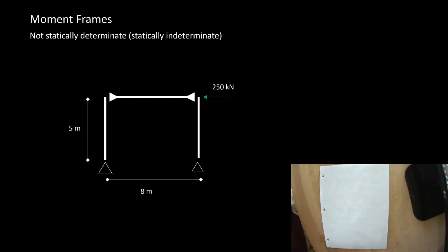Okay, so when we were looking at the braced frame, we didn't know how much of the load went to this X reaction and how much went to this X reaction. So we went through and started the process. And then when we solved over here, we saw that there was no way for a reaction to get to this point. And we calculated and saw that it was 0, which left us with the ability to calculate the reaction at the other side.